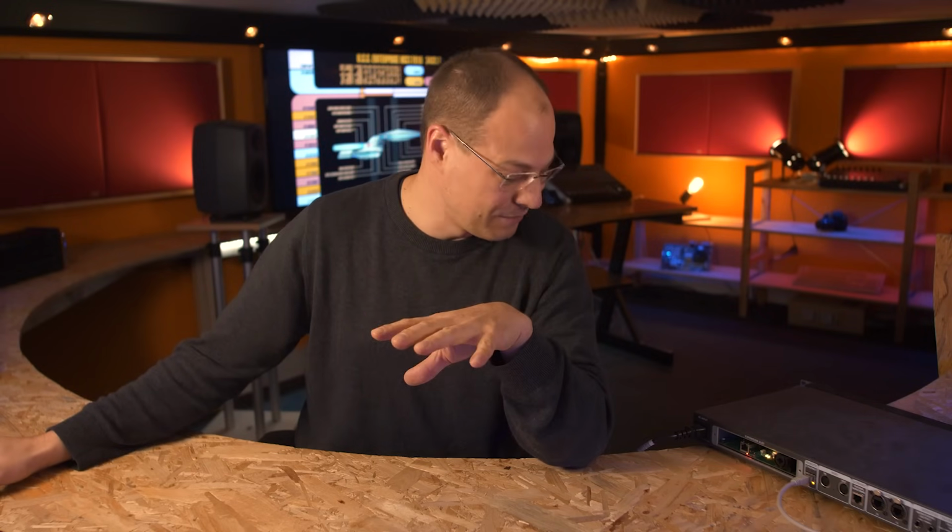Okay, so we have to do a bit more digging here. There are several more communication lines on the original PCB I did not check. I was hoping that the UART connection and the TDM connections are enough, but doesn't seem so. So first I have to disable everything, remove the card and plug the other card and do a bit more digging on the other signals and see if it is then working.